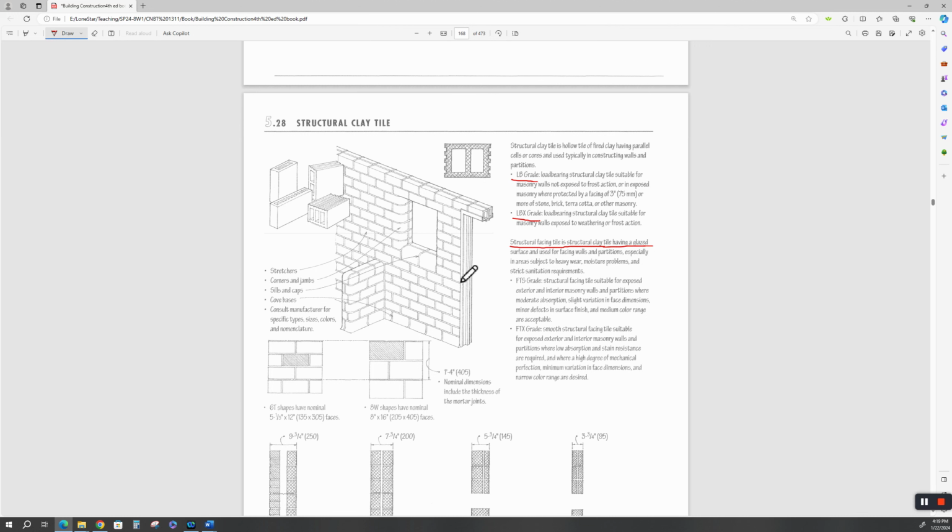Okay, I used a lot of this in wastewater treatment plants in the operation rooms and stuff like that. Why? Because you use a high strength grout in here with a plasticizer in it, which makes it very, very water resistant. There's a coping down here, the cove bases, and you come in here with a water hose and hose down these walls because all this is clay. Glazed. It's a glazed surface.